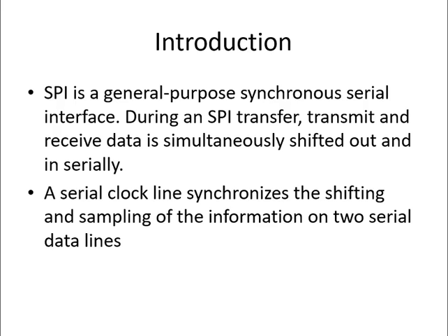So we are having simultaneous data transmit and receive operation available in SPI. That is the biggest advantage of SPI. So speed is naturally doubled as compared to I2C. Then it also requires a serial clock because it is a synchronous serial communication. Serial clock line synchronizes the shifting and sampling of the information on two serial data lines. So always the data should be sent in synchronization with the clock signal of SPI.